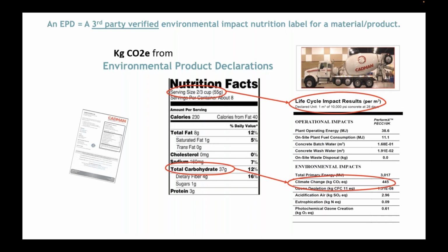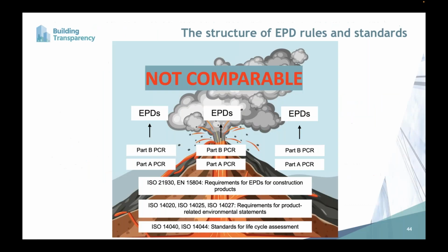I'm going to focus on environmental product declarations and not generic data. I could do a whole other presentation on generic data and projects we're working on there. But really with EPDs, it is trying to get to those metrics around all sorts of impacts, but really the carbon emissions is where people are focused today. And they can be cradle to gate or cradle to grave, as Terry mentioned. But when we start to look at EPDs, this is really, I think, repeating what Terry said, but hopefully in a way that's memorable for you.